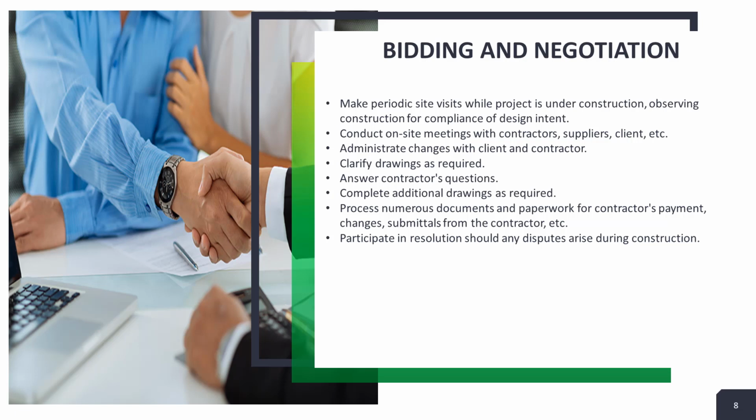The work in this phase typically includes the following: prepare documents for bidding, such as the invitation to bid, instructions to bidders, and the bid form. Advertise the bid and solicit contractors to bid on the project. Coordinate and provide bid documents to bidders.